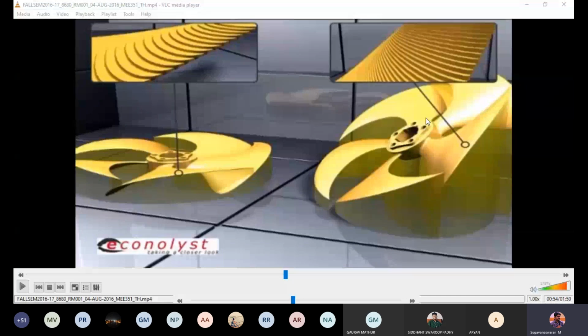So we'll move to the next session, next topic. CAD model is done, part orientation is done, and I have the support. CAD modeling is done. I saved that in STL format, that is, connected triangles. Then later it is oriented in some way, and based on the orientation, the support structure is generated. So two examples I have given for orientation. Once the part has been oriented and the support structure has been generated, let us take the first case as the best. Based on the first case, the next step is that I have to slice the model.